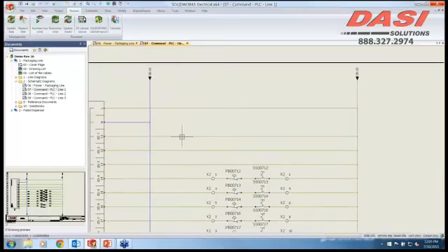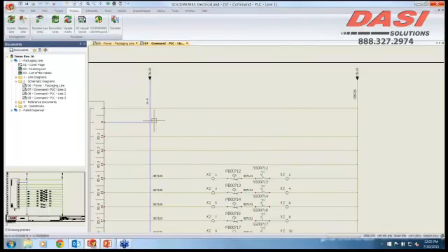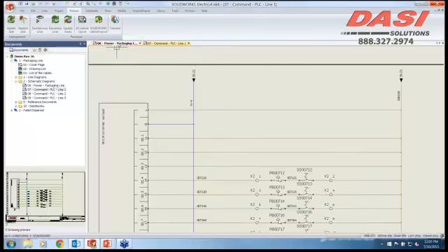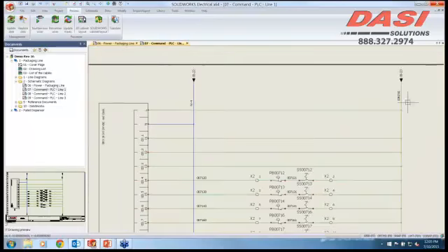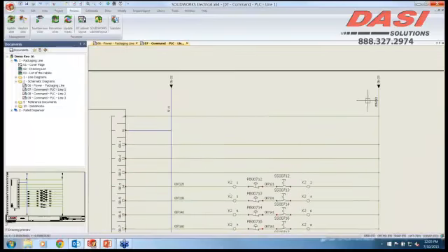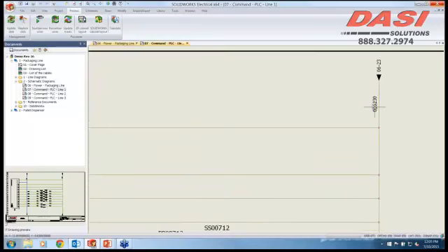What's nice is that you have your go-to origin and destination arrows that we had before. So when you are numbering new wires, those wires translate from the previous page, come straight through our transformer here, and go directly to the next one, and you are not having to worry, did I connect it up right? Did I move the wire number incorrectly?